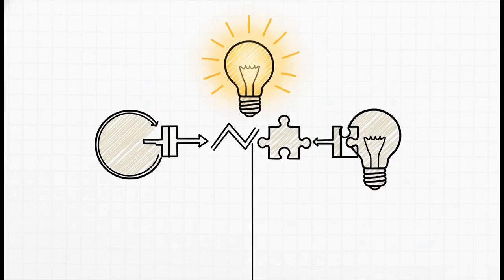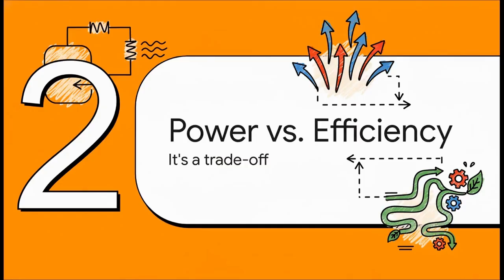Where's that sweet spot? Well, it happens at the exact moment the load resistance becomes equal to the source's internal resistance, when RL equals RI. And that, in a nutshell, is the maximum power transfer theorem. But, you see, this brings us right back to our original puzzle. If matching the resistance wastes so much energy, why would we do it?